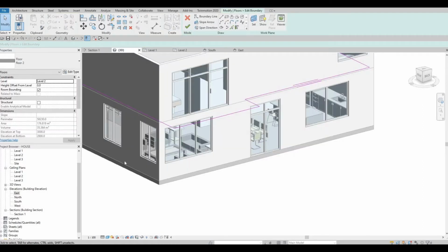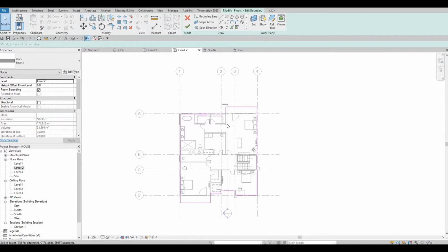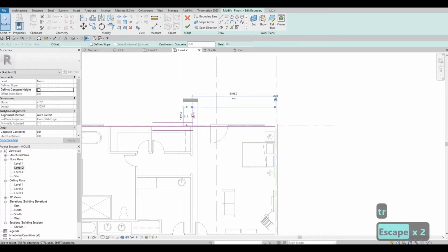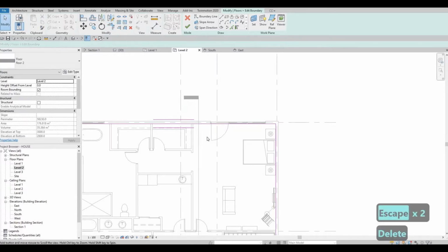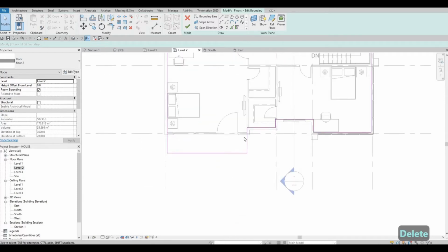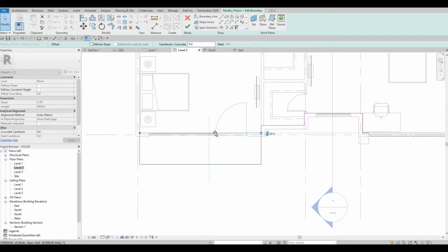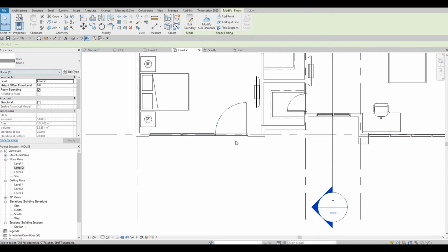I'm gonna delete it, as I will use the extrusion part to create that design there. So this is a level 2, and then I'm gonna trim and extend it, and then now I'm gonna delete this part. Same here. So here I'm not gonna delete anything, I'm just gonna pull this back. Click finish, and let's see.